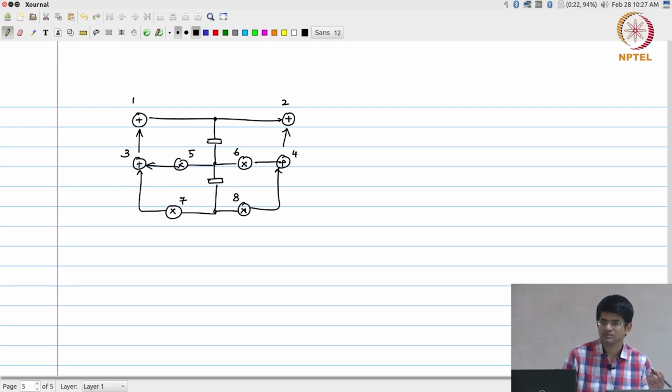What is that number? Can I reduce the critical path to 1 multiplier, or is there anything else in the structure of the graph that prevents me from bringing it even that low? What is that? It's a cycle in the graph. What do cycles imply? Iteration period bound.